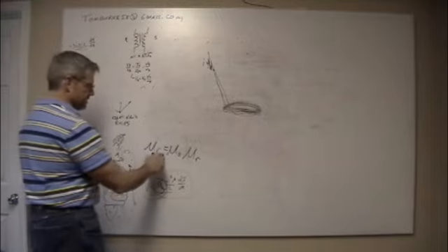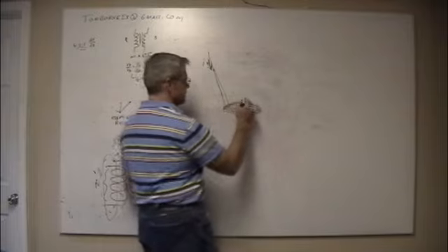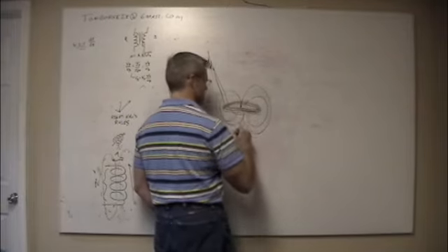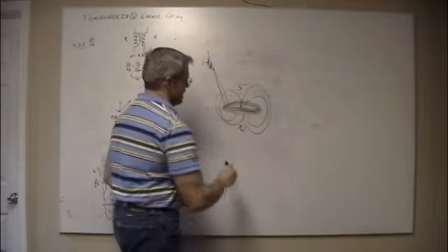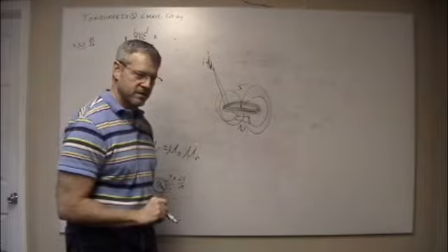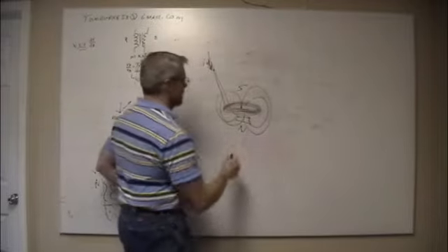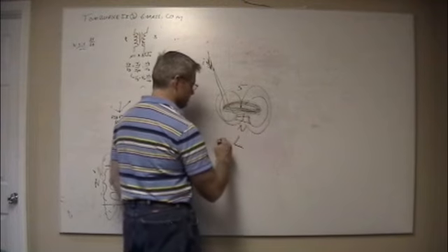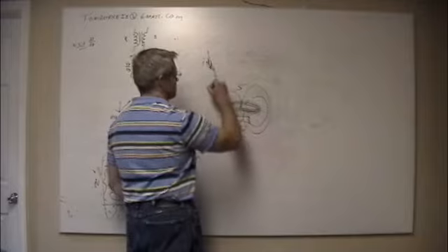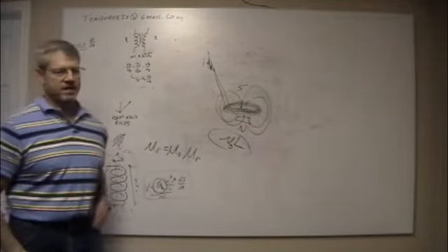If this is a piece of metal, then you changed your mu. I've created this magnetic field that's, say, north and south, and now there's a piece of metal in the ground underneath it, or in the wand that the guy's passing over you. It changes the L, mu changes, L changes, current did not change, so voltage has to. Bang, I just detected metal.